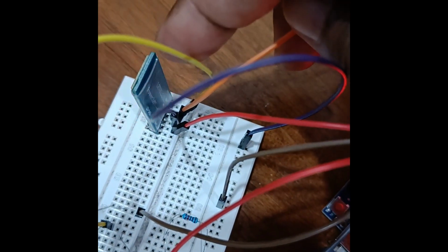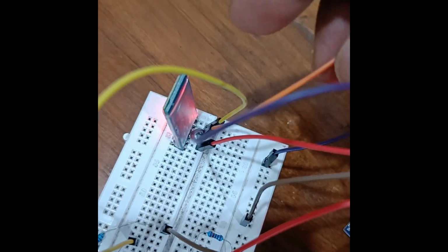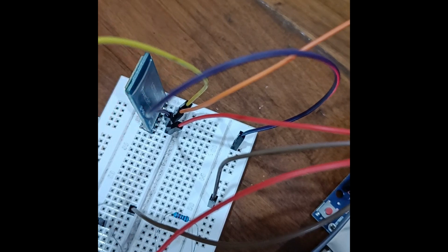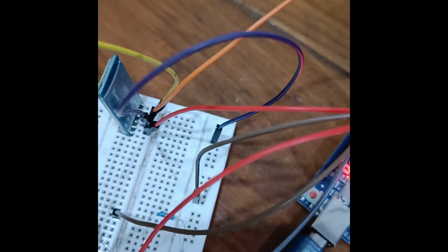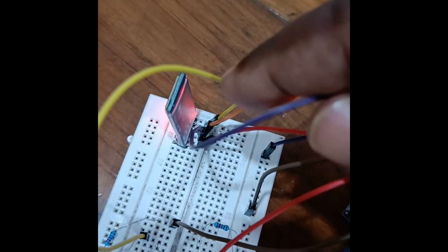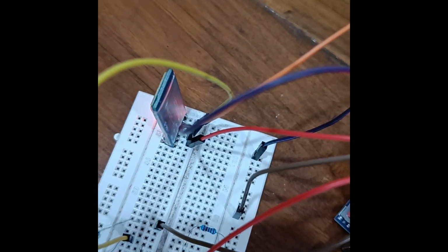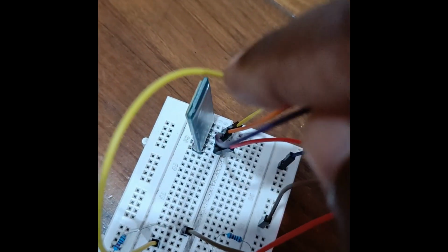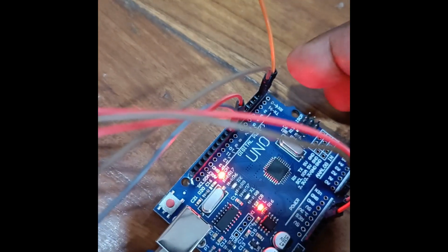The Bluetooth module is getting the data from my cell phone and transmitting. So when it's transmitting, the board will receive. It is receiving over here at the receiver point, and when the board transmits, it should go as a receiving to this particular Bluetooth module. So it is opposite. The transmitter over here connects to the receiver of this, and the transmitter over there connects to the receiver of this board.